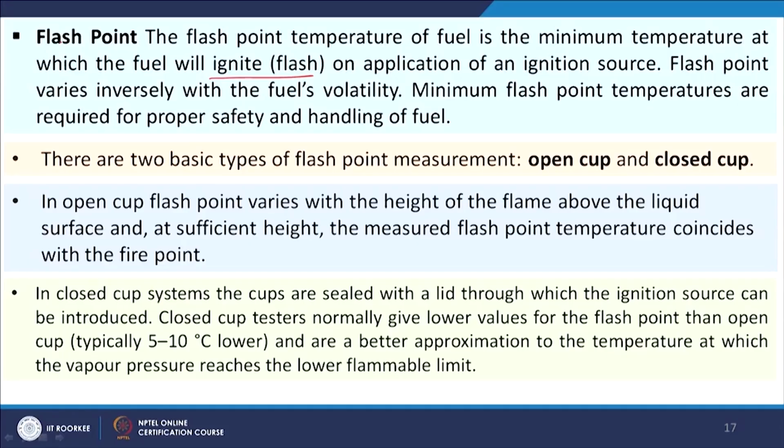Flash point and fire point are properties of the liquid fuels which are produced through the refining of petroleum crude, and they are determined in open cup and closed cup systems. In the open cup system, the flash point varies with the height of the flame above the liquid surface, and at sufficient height the measured flash point temperature coincides with the fire point.